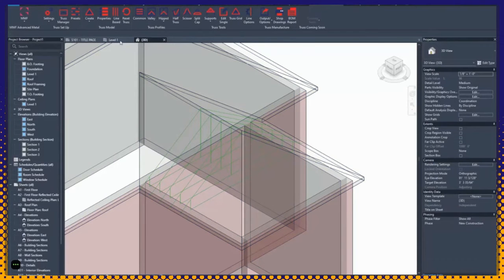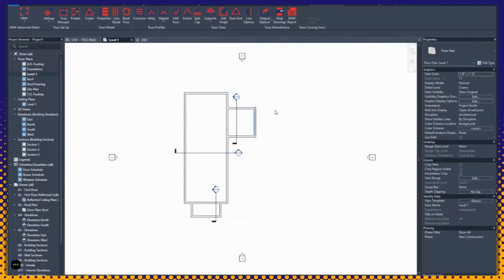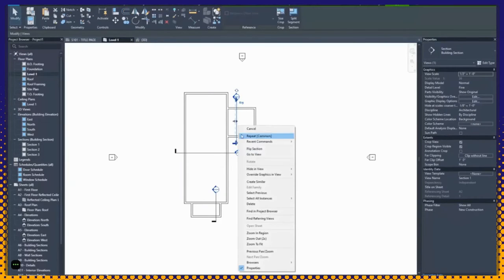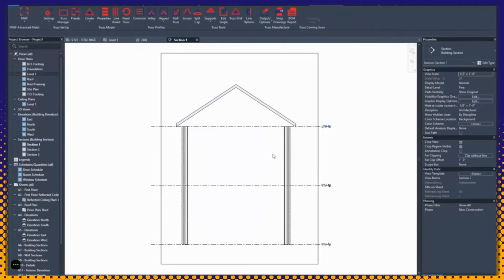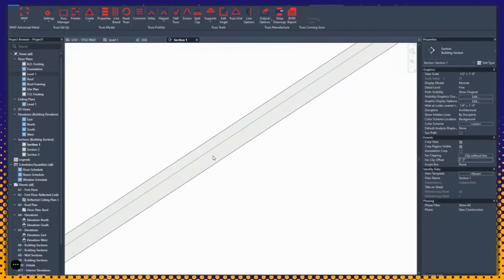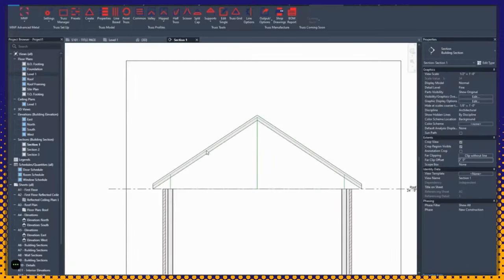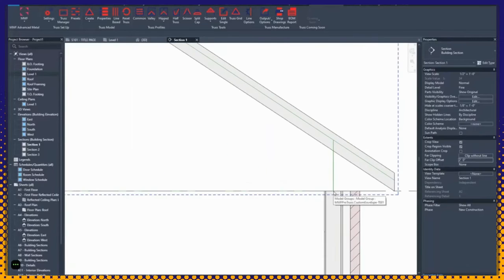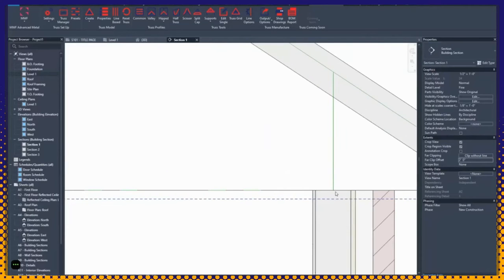And now I'm just going to go ahead into level 1 here. And then I'm going to show you what that truss just looks like right now. Let me make that 2 feet. There you go. So here you can actually see that's your 2-inch offset from outer face. And then this is your heel height, and your heel is placed right in the center of the core layer.